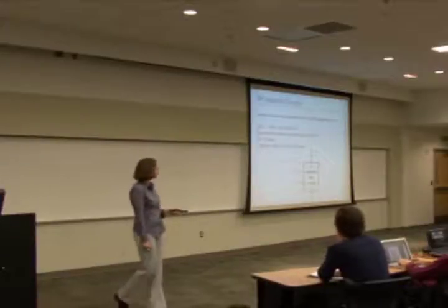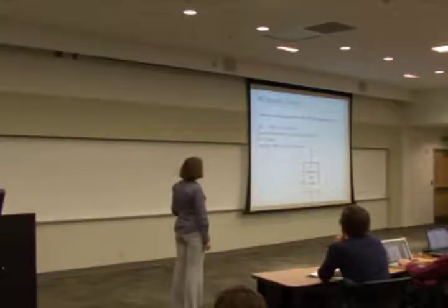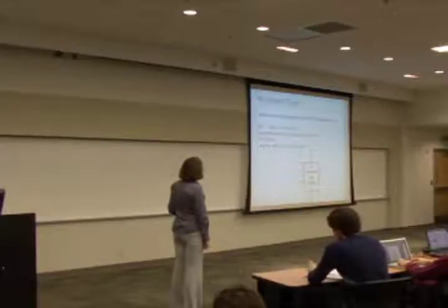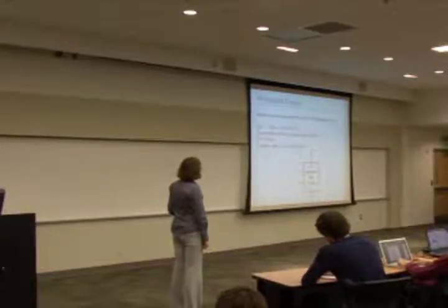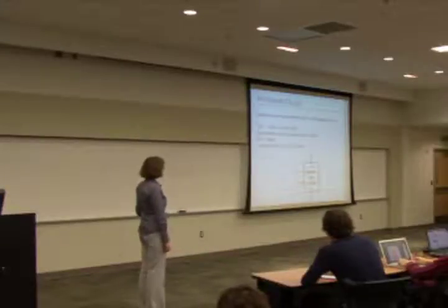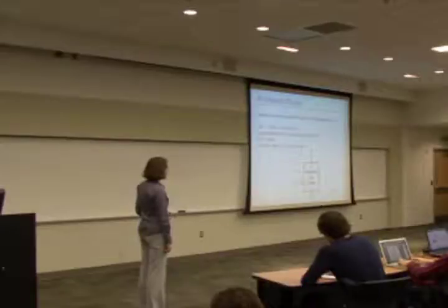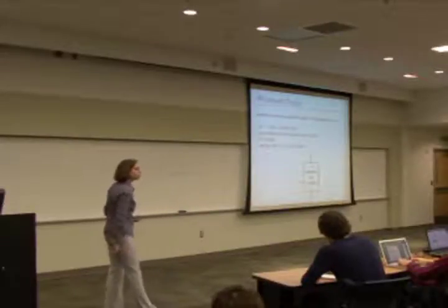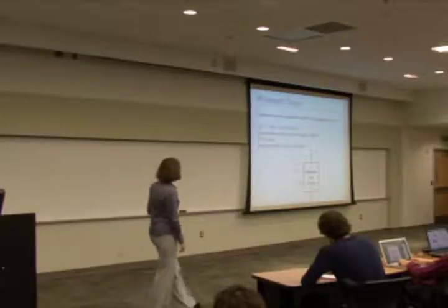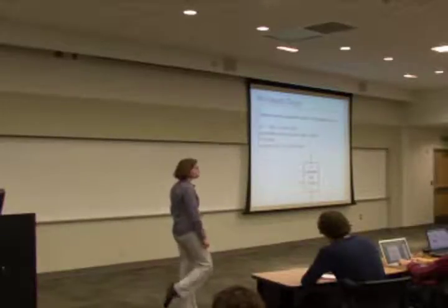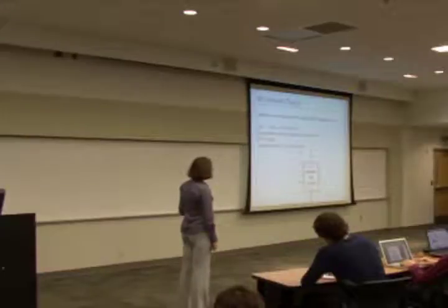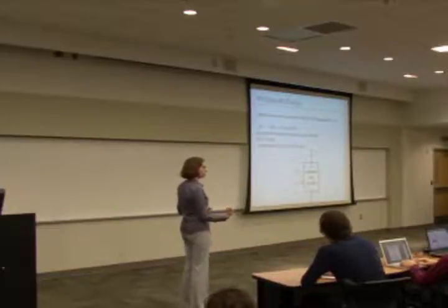So let's see again, how do we represent these registers? Basically, we will use 16 of them in LC2200, and those 16 registers will have 32 bits. So how many wires will be here, this D in? And how will be the out? Okay. And this write register is basically a signal that tells you when to write into register something.